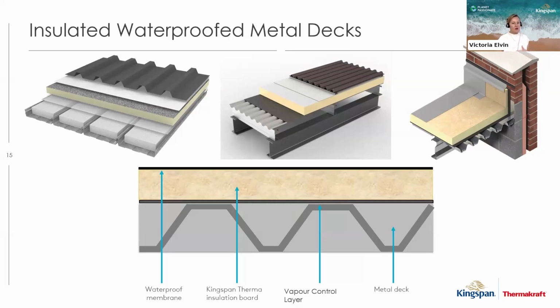It can even be used as an overlay system on an older roof, reducing demolition costs and containing elements such as asbestos, as you see in the top left image. There are many different styles of this type of roof, some with a profiled metal on the top, which would be direct fixed the whole way through the system, or some that have a membrane system on the top as well, which might be adhered or glued together as part of a system. Each system again has its own advantages, and each proprietary partner will be able to explain what is most suitable for their design.